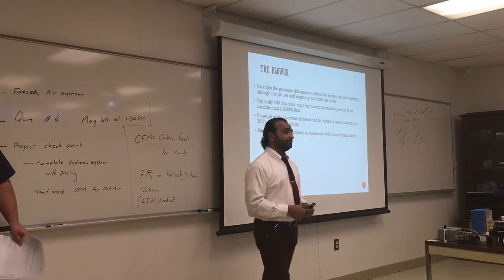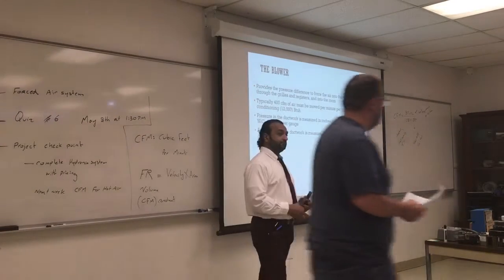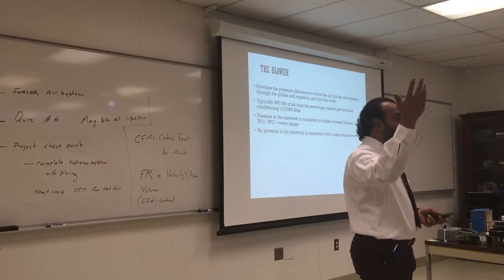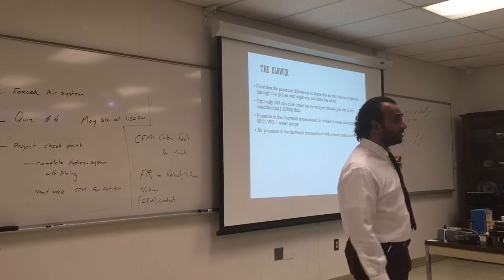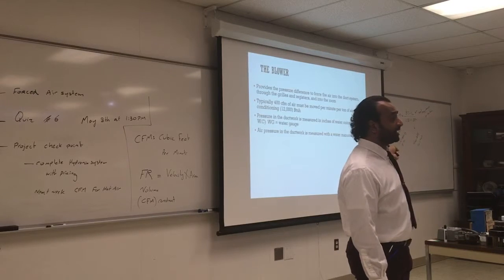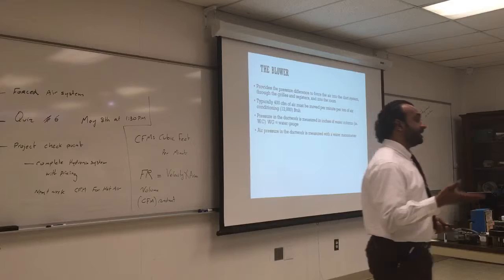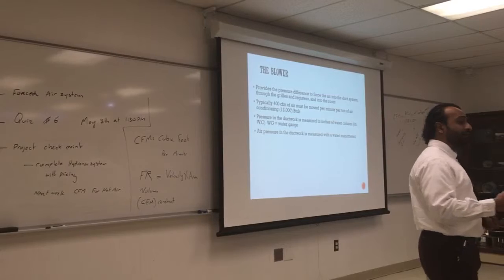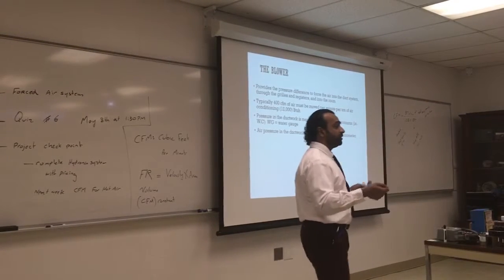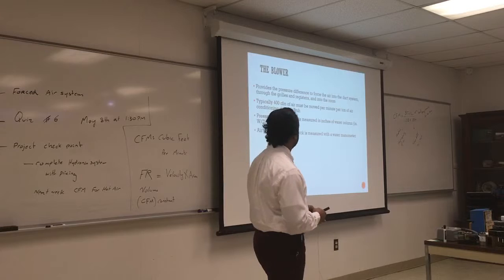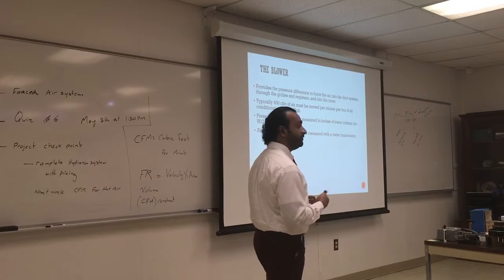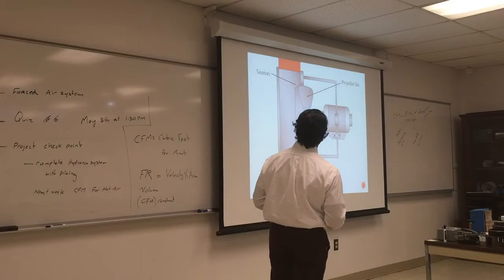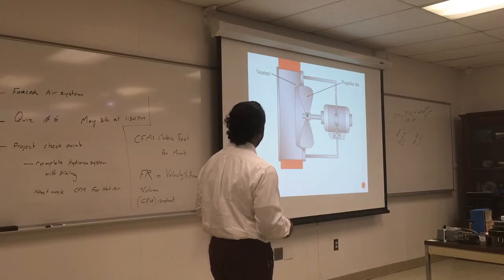Where do we use the manometer? You can use the manometer when you don't have access to the airflow. You're outside. You want to measure the pressure in the duct. You have no access to the airflow. You can't stick a fan in there. You can't stick a flow gauge in there. So you go using the pressure, and there's a calculation for that, which I'm not going to get into. But if you work for a company that installs duct systems or ACs, probably you have to know how that's done.